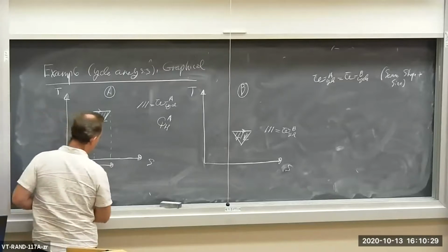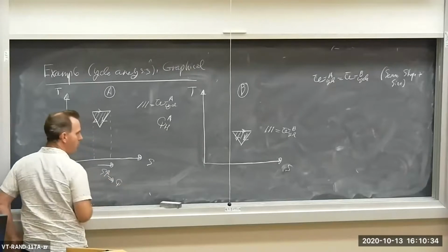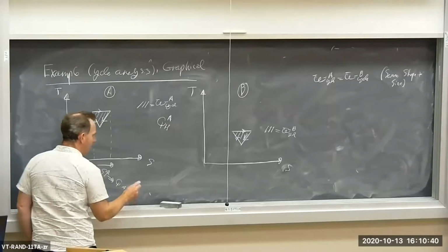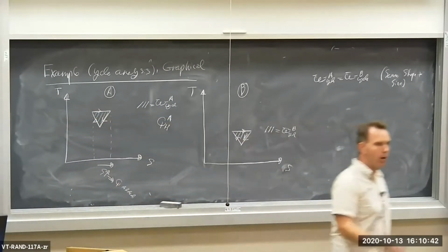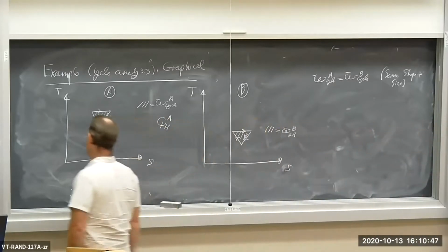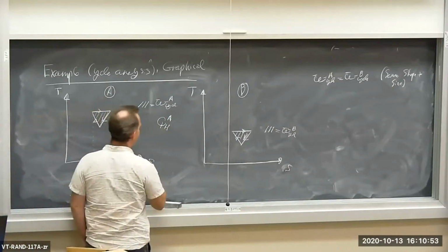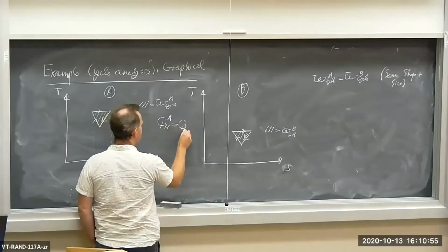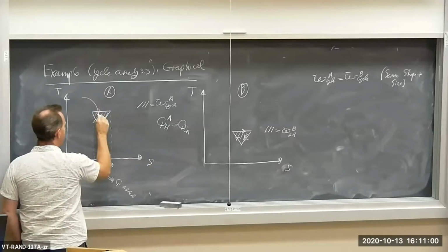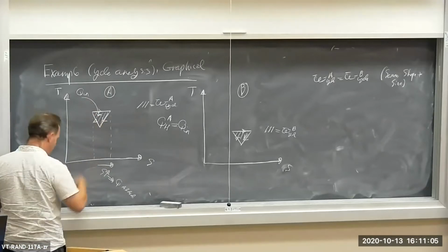And if entropy goes up, so S is going up, that means Q is being added. And we know that Q is being added from the hot place into my working fluid. So Q high A is actually equal to Q in. Okay, so heat is being added in this part. Q in is being added in this portion of the cycle.